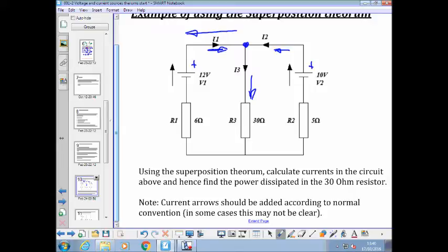Can you remember? That will come out as negative. So what you mustn't do with these circuit theorems is, if you get a negative current, necessarily think that's wrong. What it means is the arrow you put on in the first place, as long as you've followed all the rules correctly, was actually a wrong assumption, and that battery's not delivering current, it's taking it in, it's being charged.